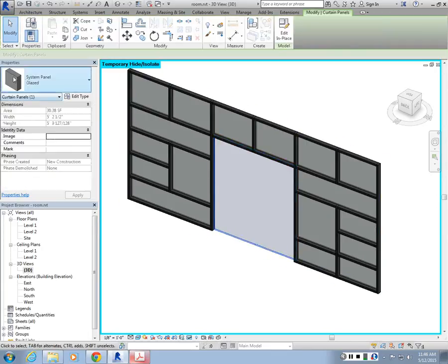And this shows me in properties what that object is. It's a glazed curtain wall system panel, which is glass basically. It's a single glass panel. And I want to click on this drop down, and I want to change its type. So I can make it empty if, let's say, you're creating a kind of open air system, or maybe this is like a louver based system, and you can make all of them empty.